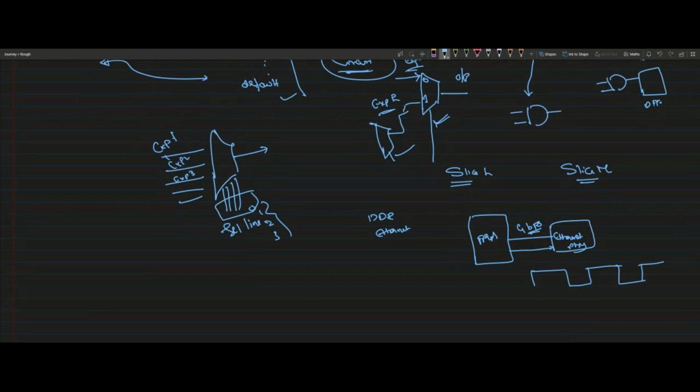So if I transmit like this and some noise gets added, some bits of this data will be corrupted. So what we do is transmit again on another line, wherever high is there, low, and wherever low is there, high. This way. We call the noise additive white Gaussian noise. That adds up, right? Both the channels will be added with the same noise.